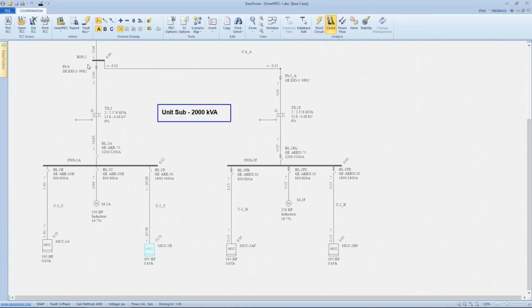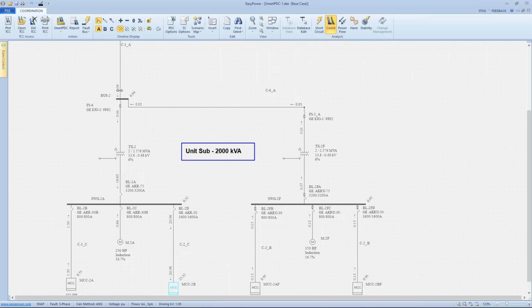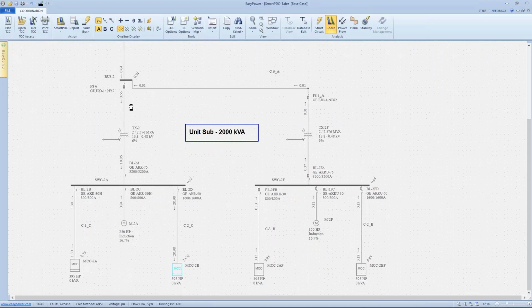And that is during the first half cycle of current. During the first half cycle of my fault, I will have 130 amps contributed to the fault from this motor control center, 130 amps contributed here, 120 here. So that total of 370 amps is contributed up through the transformers and back down, and it's part of the 18850 that's coming from upstream. And just to make note, the utility is supplying 640 amps, and this other contribution current is a little over 10 amps listed at the 13K level. So it all contributes into my fault.